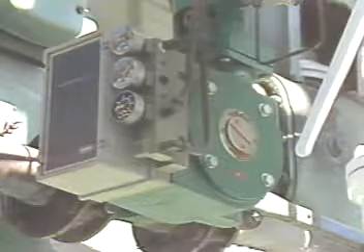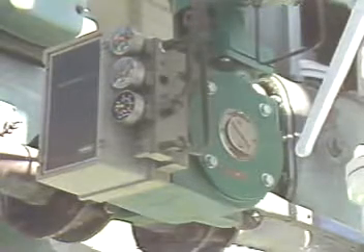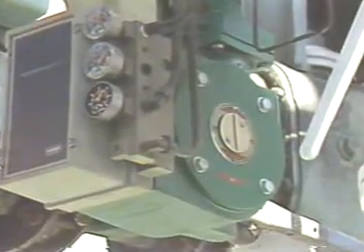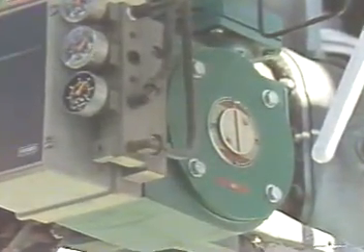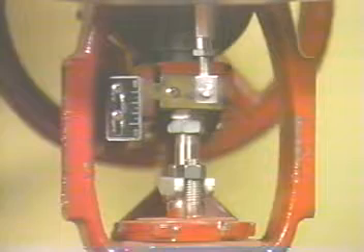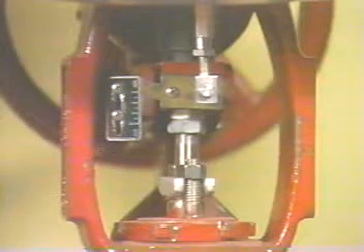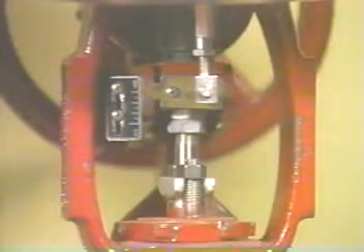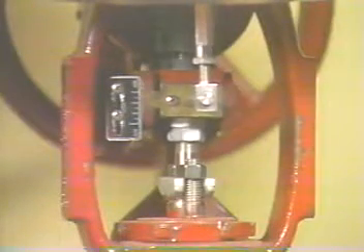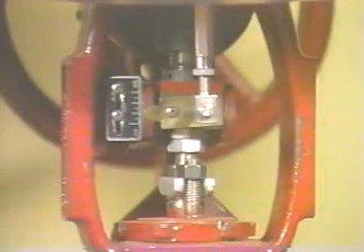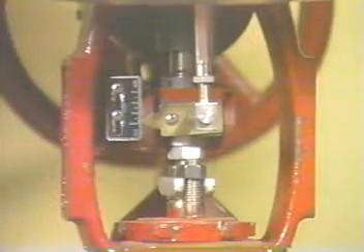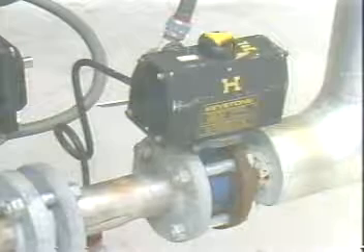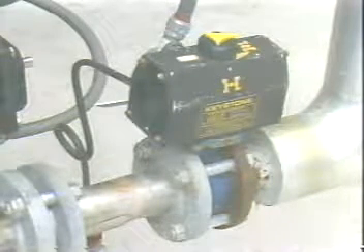When a control valve is used in a batch process, its primary function may not be modulating fluid flow. It's common in a batch process to use a control valve to start and stop the flow of a fluid, particularly when a precise volume of a fluid is being measured. In this situation, the shut-off capability of the valve may be a more significant design consideration than it was in a continuous process. In another application, quick opening or closing may be the primary concern.